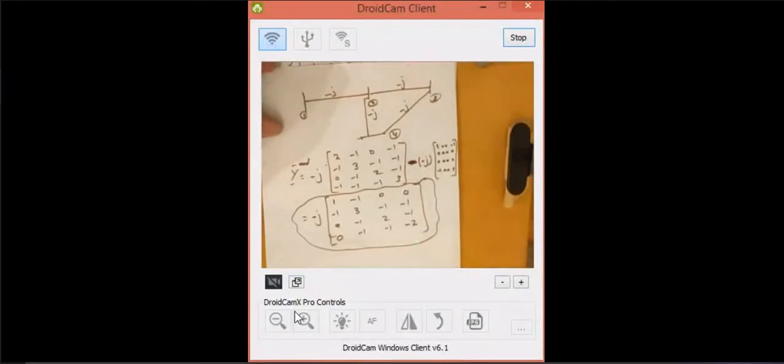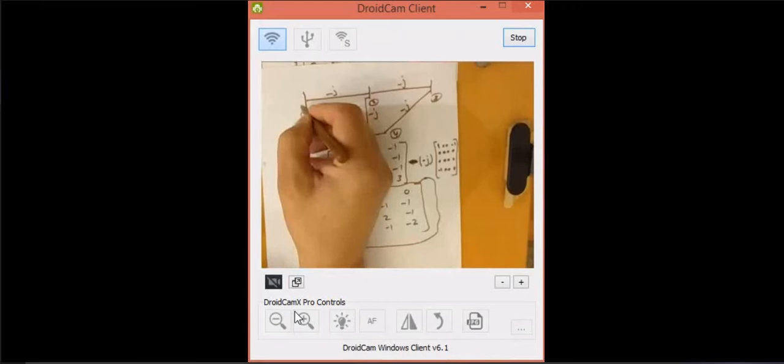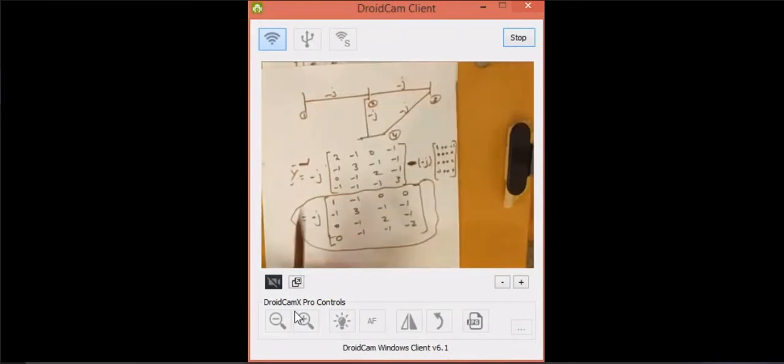And here, keep in mind that any line, if we remove or add any line, is going to affect 4 places: I I, I J, J I and J J. The line we connected here means that it's going to affect 1 1, 1 4, 4 1 and 4 4.